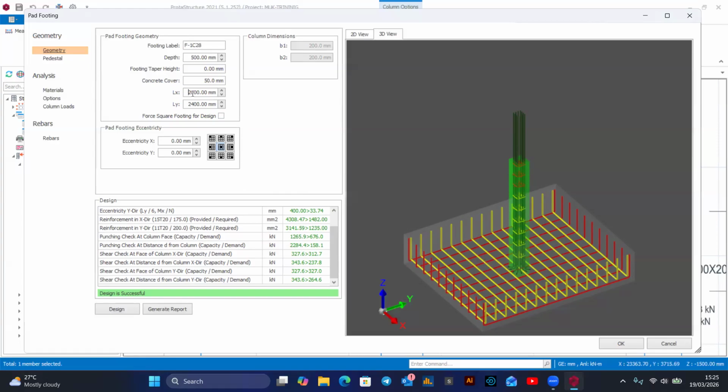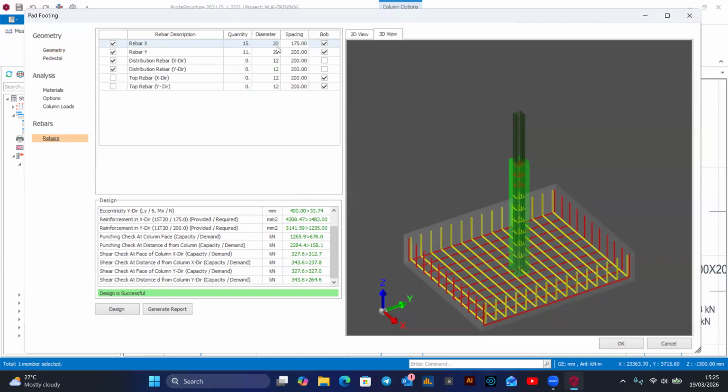So you have a big area with reinforcements which are T20s, okay? So you now resort to reducing the reinforcements to a lower diameter, okay? And check, it's better you have a lower diameter of reinforcements like in a big contact area of a footing.